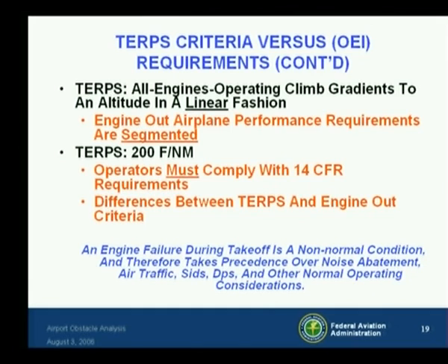To continue, TERPS typically use specified all engines operating climb gradients to an altitude in a linear fashion, rather than a certificated one engine inoperative airplane performance requirements, which are segmented. You remember the slide with the 3 segmented climb on the profile. Operators must comply with 14 CFR requirements for every takeoff and for the development of takeoff performance data and procedures.